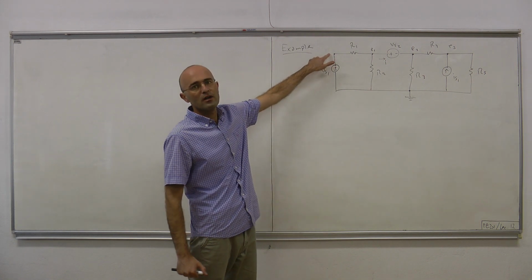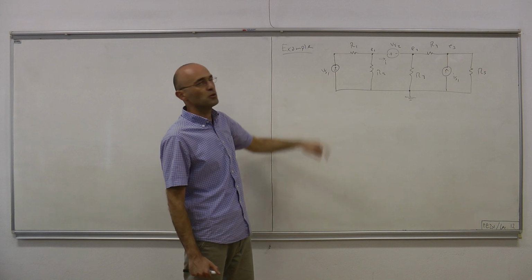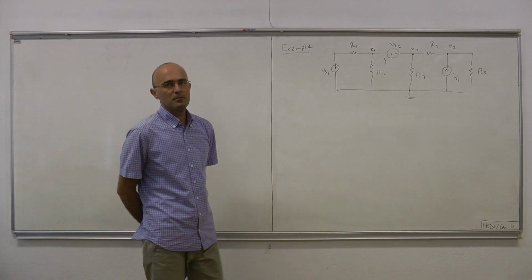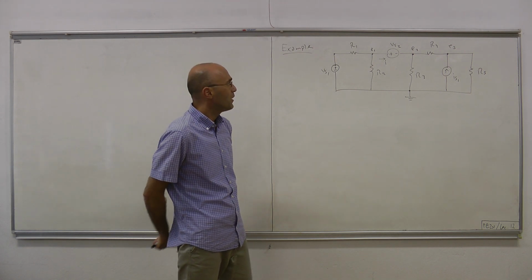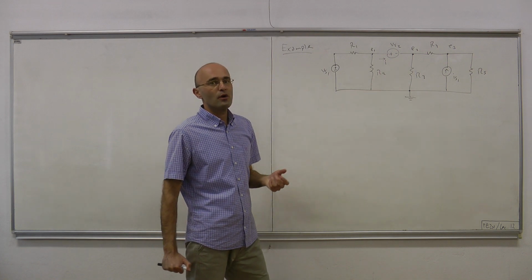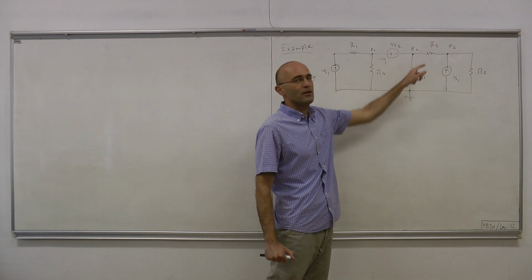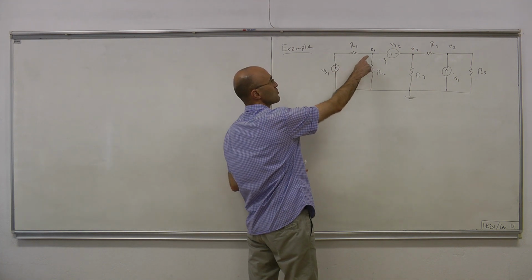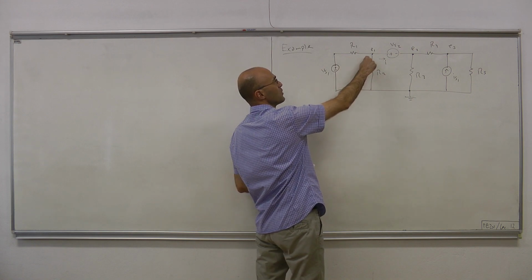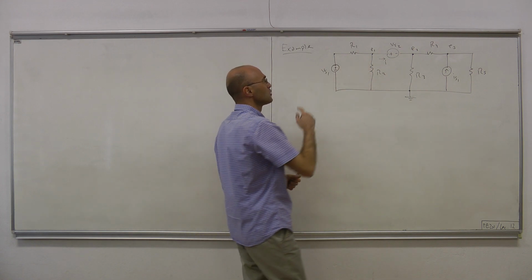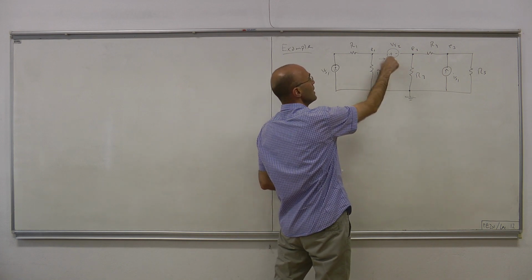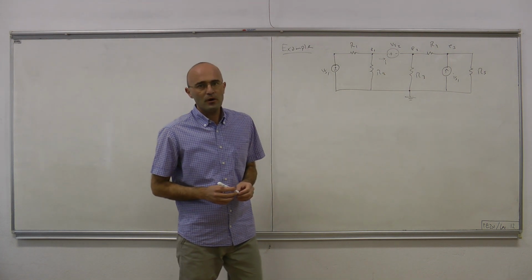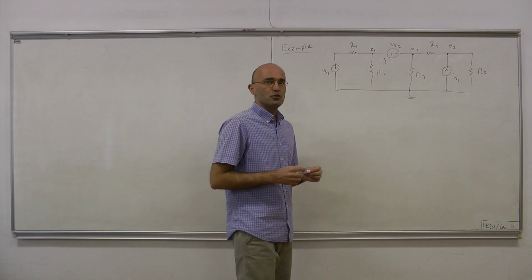Therefore, we direct the voltage, this node voltage, it equals Vs1. Since it's known, this voltage source doesn't cause any problems. Whereas this voltage source, if we try to write KCL either at this node or that node, will present a slight problem. You can write this current in terms of node voltages, but when you try to express this other current, you cannot use Ohm's law because this is not a resistor. Therefore, it's not apparent what to do with that current.